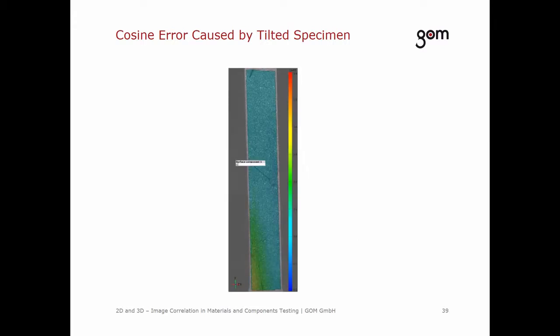The displacement in z direction shows that the specimen twists at the bottom. The left part moves further forth, the right part moves further back. This effect can occur when the specimen is not clamped optimally. For example, when there is grain between the wedge clamping jaws, or due to small movements under growing load.